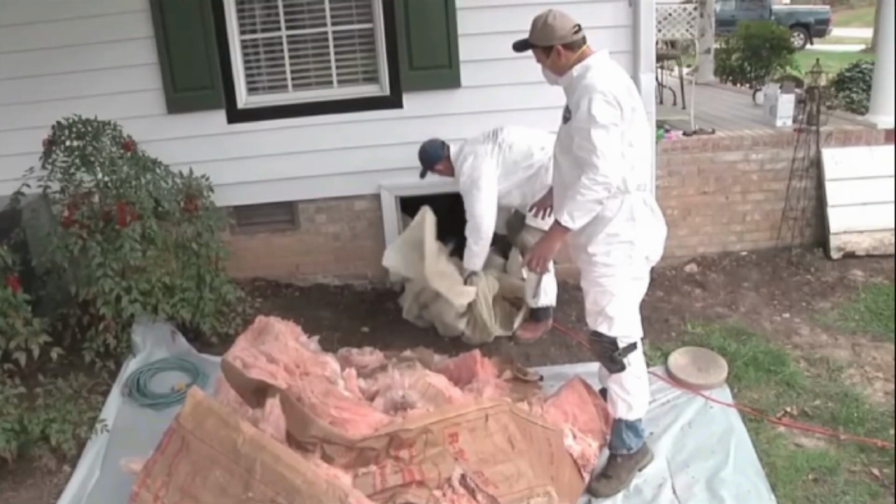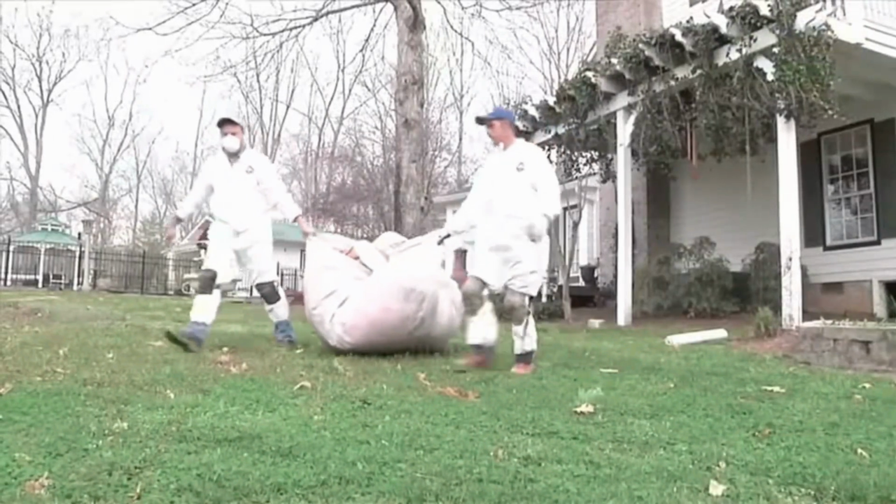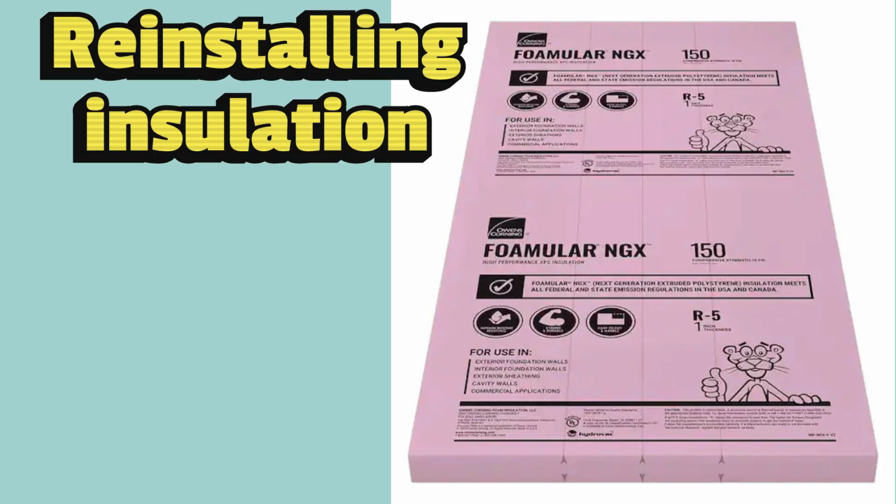As you're pulling the insulation from the bottom of the subfloor, use a tarp to stack the insulation on and pull it in batches. This is much easier than dragging it piece by piece out of the crawl space and to the haul-away point.